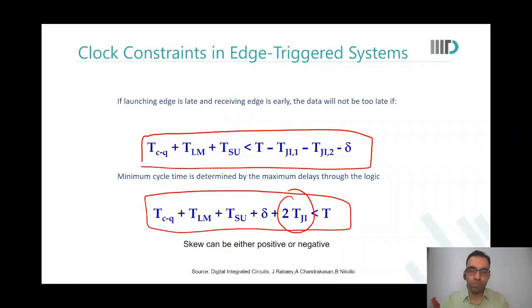So can we say that because of jitter, the original time period of the clock from the source was impacted? Yes. But you are doing sign off at one frequency. You've done the sign off, but now you need to leave the margin for jitter, because your STA tool cannot take care of these variations, can it?